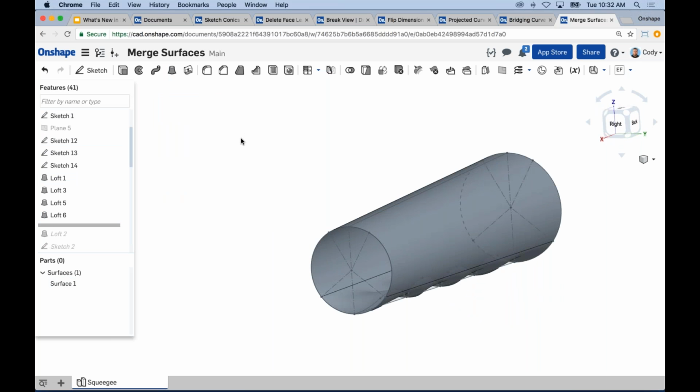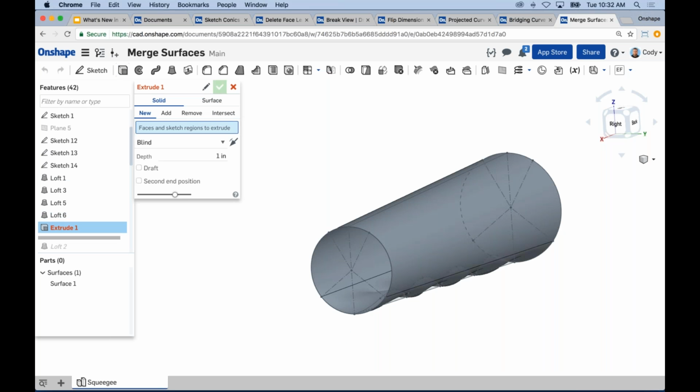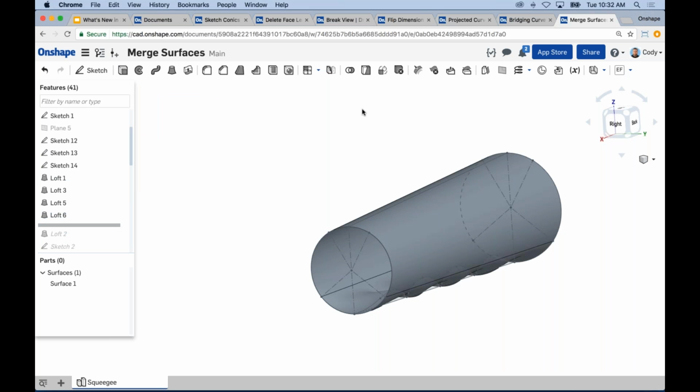So if you're doing this kind of face-by-face manipulation of surfaces, definitely realize there's a new option. It doesn't matter whether it's extrude, revolve, sweep, or loft. Under surface, you'll have this new option for add. And of course, the ability to do things like knit surfaces manually as a separate command is definitely something that's high on our list of priorities.